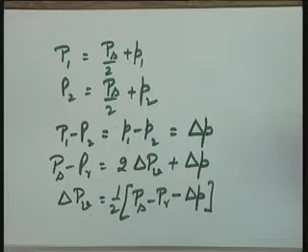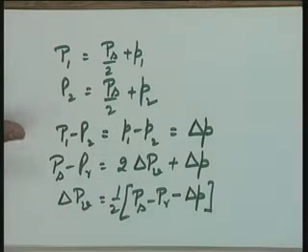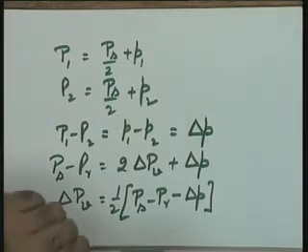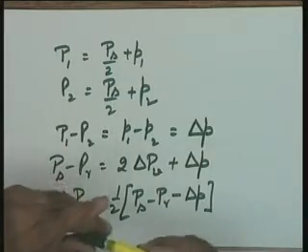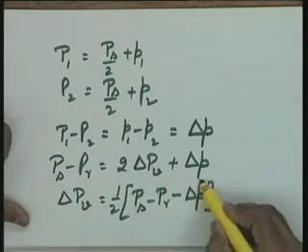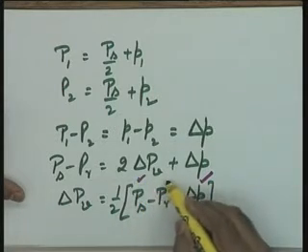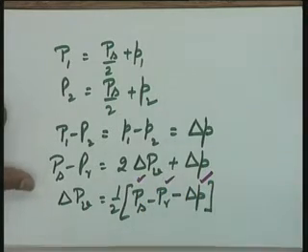What I want to say through this relationship is that the pressure drop across the port, once the system has been designed properly, is a function of del P, because this Ps and this Pr get fixed. If the pressure drop across the port is a function of del P, what is del P? Del P is the load induced pressure.